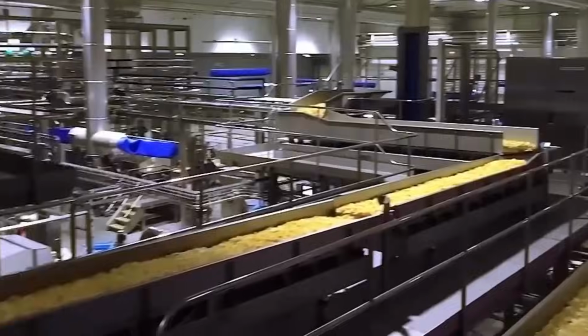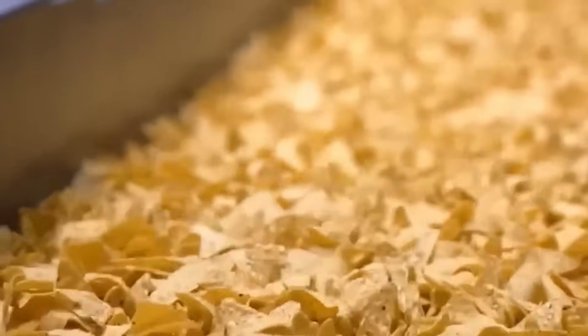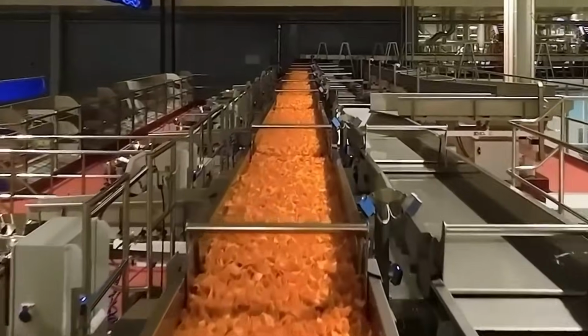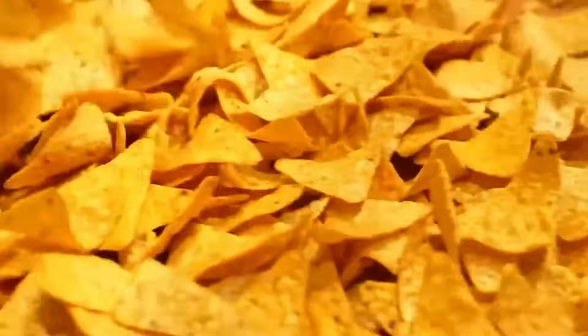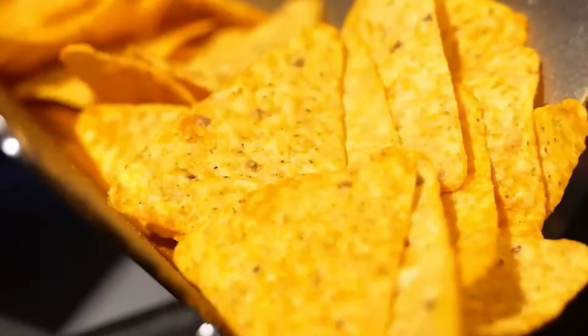The selected portions are released into a form, fill, seal machine. The packaging film is unwound from rolls and guided through a forming collar, where it is shaped into a tube. The back edge is sealed with a vertical heat sealer, and bottom and top seals are created by horizontal jaws synchronized with the drop of each portion of chips. Packages are filled, sealed, and separated continuously.